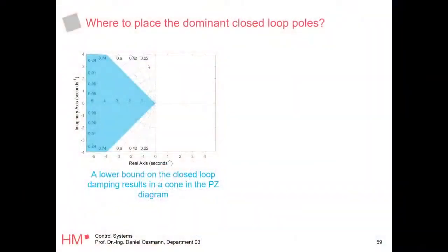For example, for aircraft, it's clearly, I think, 0.6 or something. You should not have an aircraft with a damping lower than 0.6, where 0.71 is the optimal, which we discussed, right? So what you also have is, in that way, an area which moves you away from this unstable region.